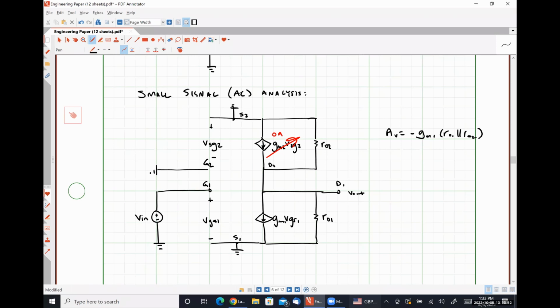So we have to pay attention to exactly how those are going to be implemented, because let's say that our power supply voltage was 5 volts, and so we wanted the bias voltage to be 4.17 volts or something like that, because that gives us exactly 10 milliamps of current. We're making this thing behave like a 10 milliamp current source, right?